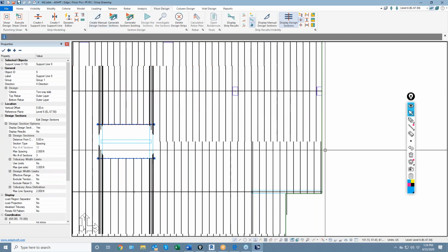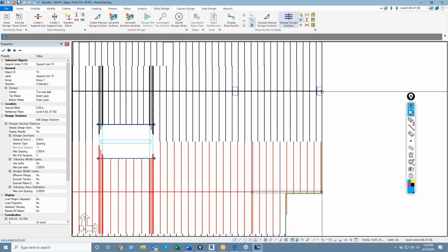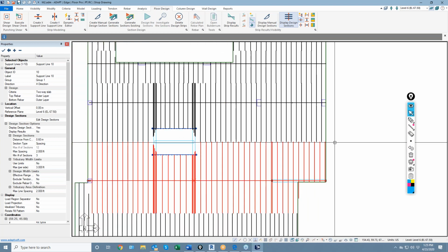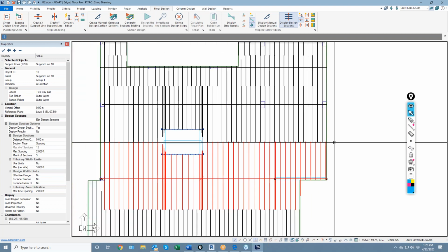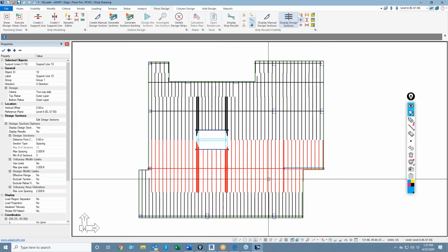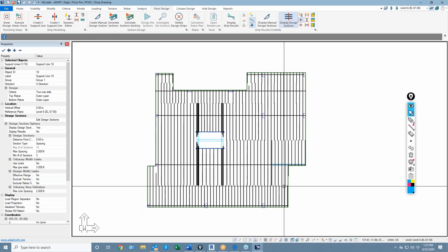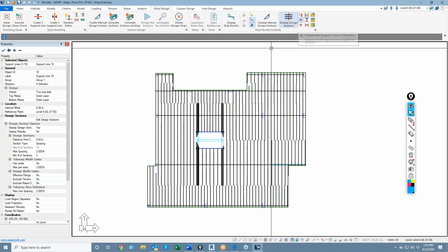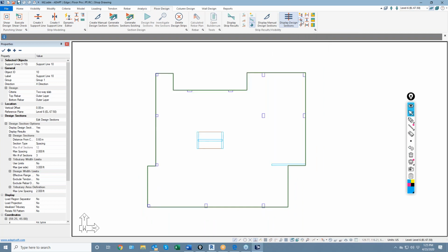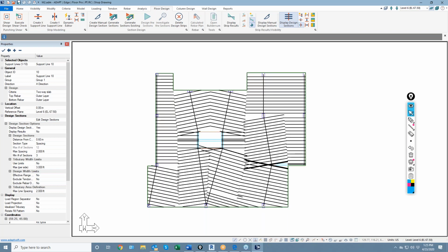Because that point is at the same position as this point, this doesn't extend over since this one was previously scooted to the left. Or you could use a splitter there also. So it's important to note the point locations and determine how they might be affecting the different section cuts. All right, so we have our strips in the X and Y directions.